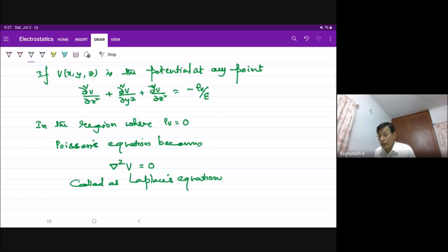Correct. In the junction region, there is something called as depletion region where immobile ionic charges will be present. The volume charge density of that region is known to us because we know the doping concentrations. Through that, we calculate E and the potential difference between the ends of the junction.